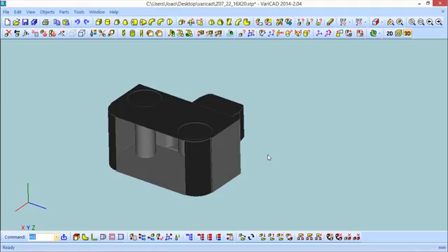If it is not possible, we may have to work with solids with missing patches, which has some limitations like we've seen, like the volume, the Boolean operations or blendings wherever it is open. And we have a lower state, the open shells, that does not allow us to work with the blendings or the Boolean operations, but at least has the advantage that it may allow us to go up to the higher state of missing patches.